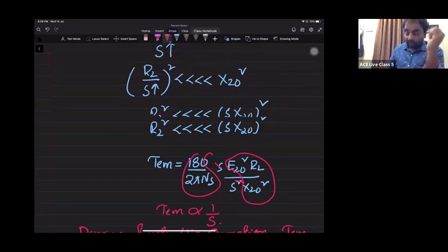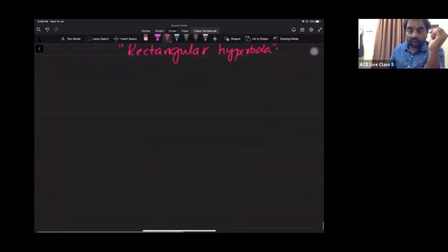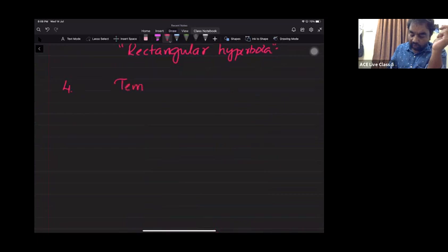All right. How many relations do we have between torque and slip? Two relations. What is that? During low slip operation, the motor torque is directly proportional to slip. It is a stable operation. On what basis can I say it is a stable operation?